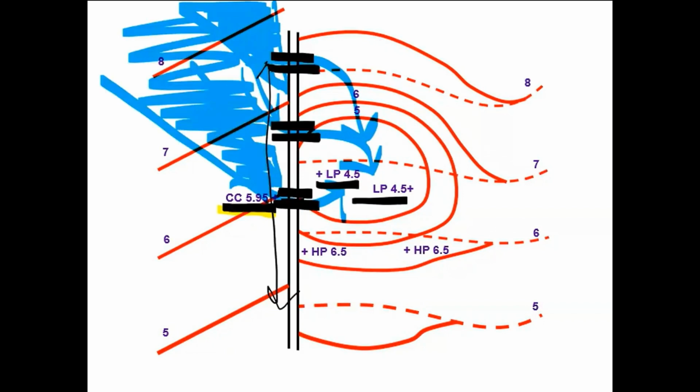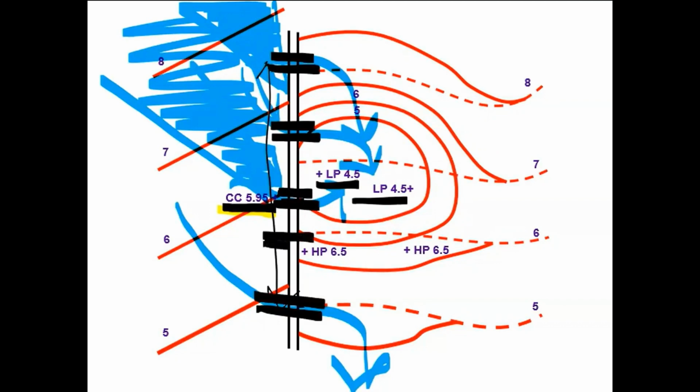What we cannot do is locate the curb cut down below the retention area, because obviously the water is simply going to run in and go down the hill. So that's pretty obvious and easy. But the other issue is we have to be careful how far down in that bioretention area we locate the curb cut. So for example, if we locate it down here on the berm, the elevation of the curb cut, as I said a minute ago, is determined by the parking lot.